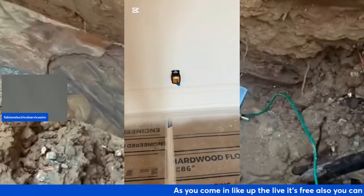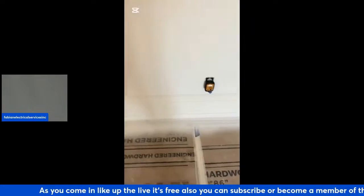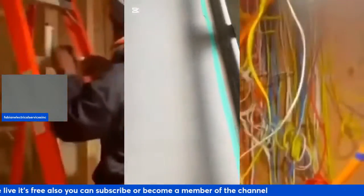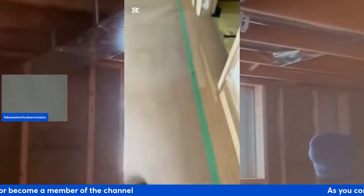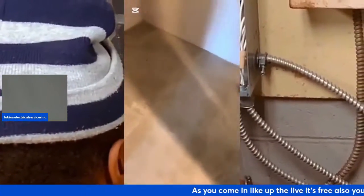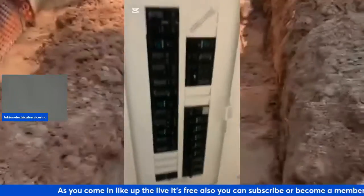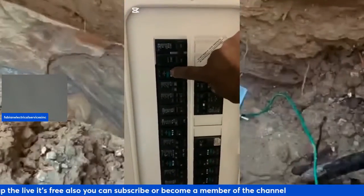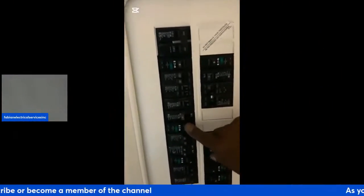A lot of times when we install the GFCI inside the washroom, it has to be a certain distance from the sink itself. Also, I just found out during an inspection that your fridge, if it's a certain distance away from the sink, calls for a GFCI receptacle.